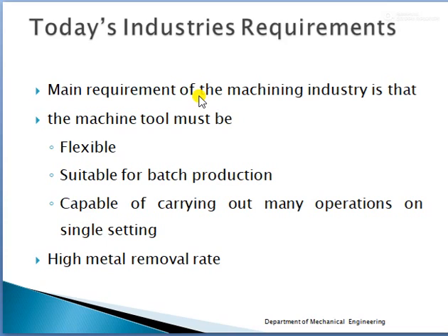Now let's see the NC machine. A numerical control machine, also known as an NC machine, is an automated machine in which the machine tool control is programmed with a series of numbers, letters or symbols and initiated in the electronic controlled system. These numbers represent the tool position, cutting speed, feed, etc.